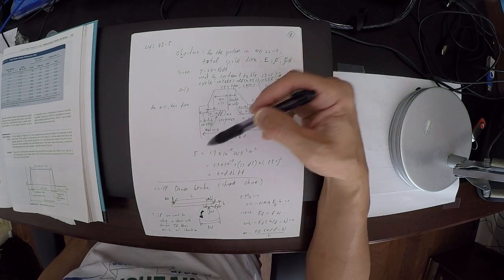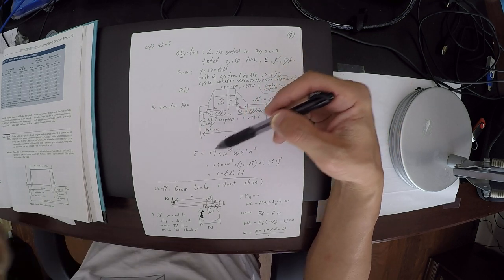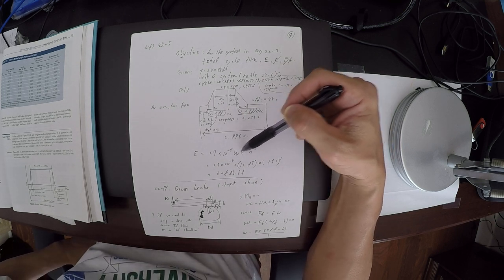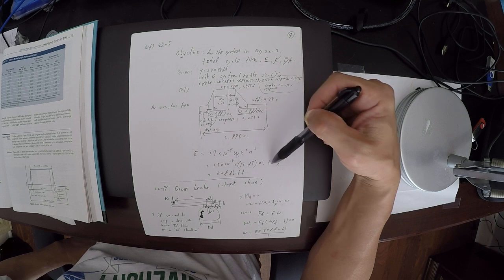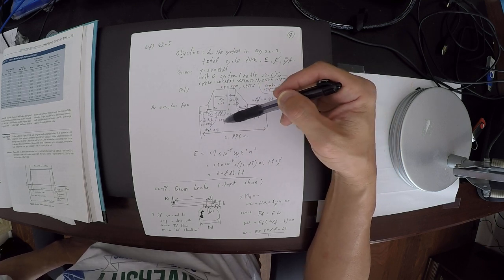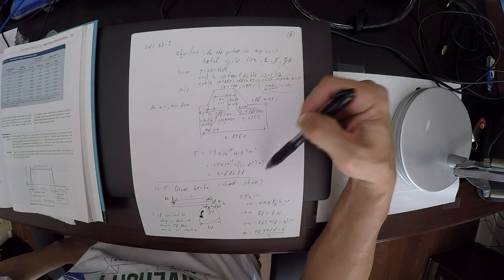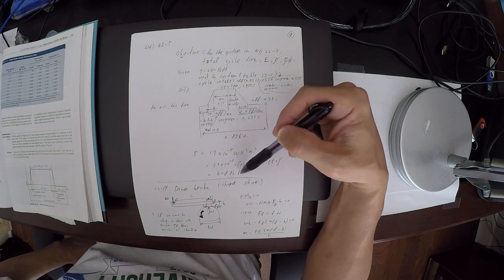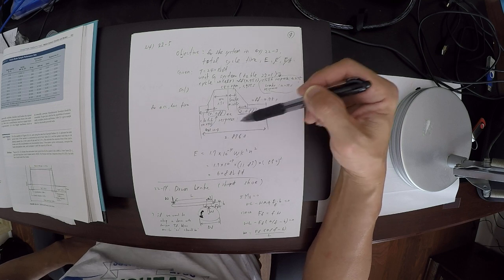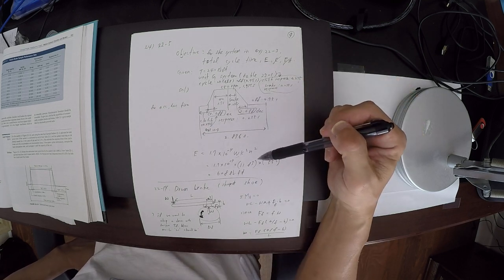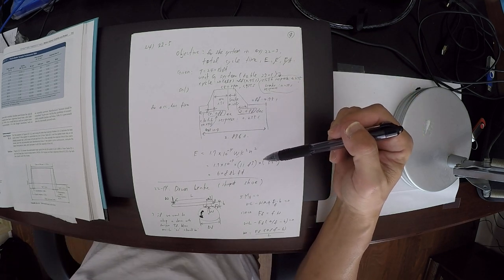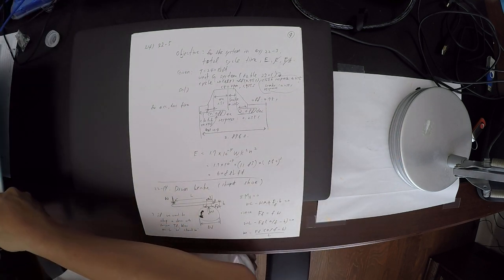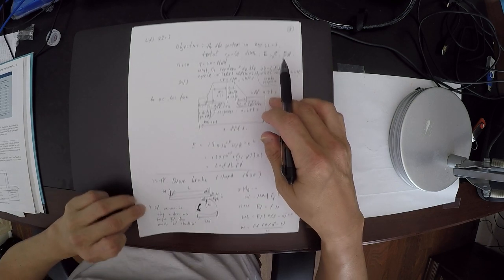And then the energy absorption is again from this equation, and you actually figure out the W and then K from the problem 22-3 we found, and it gives us the value of 608 pound-feet. That's the energy absorbed by this brake system. So that wraps up the clutch, and then we can actually move on to the drum.